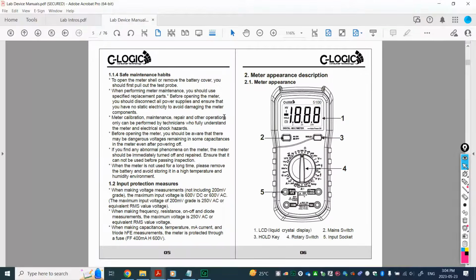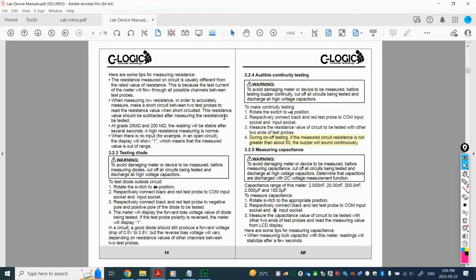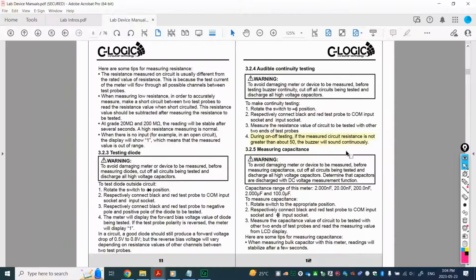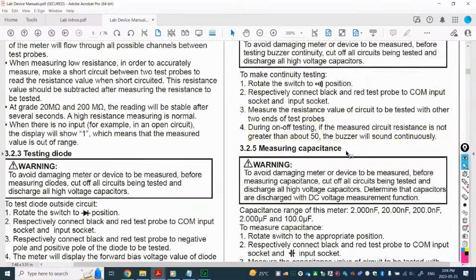A single pole, single throw, or SPST switch, has one movable arm and one contact point. When the arm makes contact, the circuit closes. A single pole, double throw, or SPDT switch, has one pole and two throws. It lets you turn a stairway light on or off from the top or bottom.